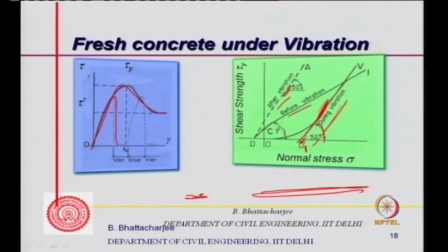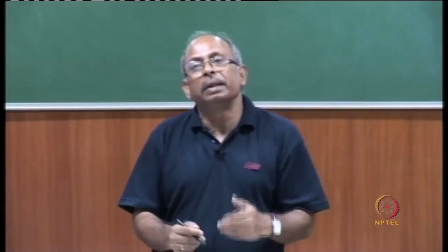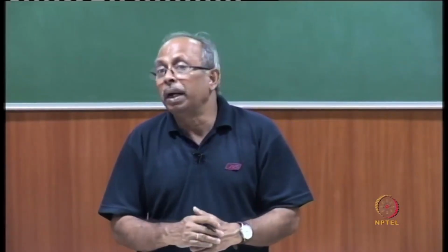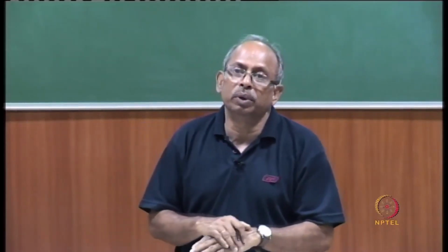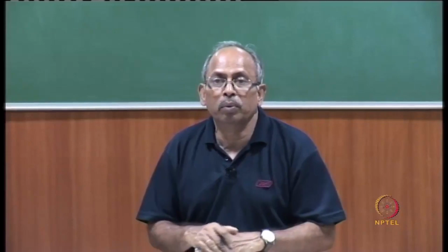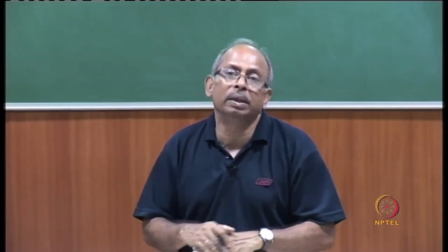During vibration, you start vibrating, yield shear stress comes down very significantly, and then you stop, again it re-establishes itself, and that's how it is. So basically, when you are vibrating, yield shear stress comes down. Therefore, particles can move. Shear movement due to the shear force can occur. It can move over each other or slide over each other.